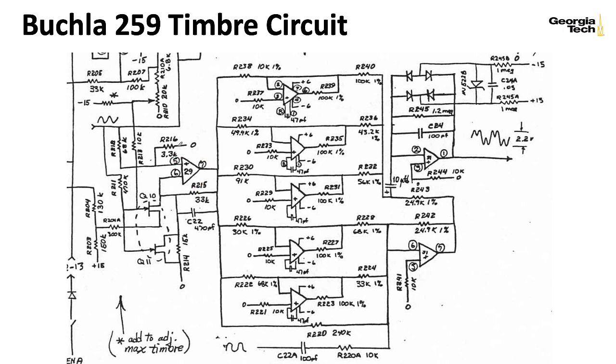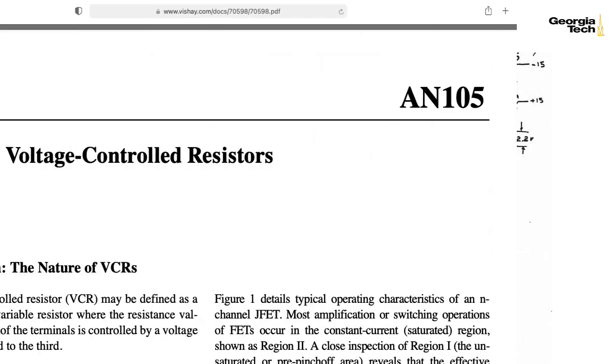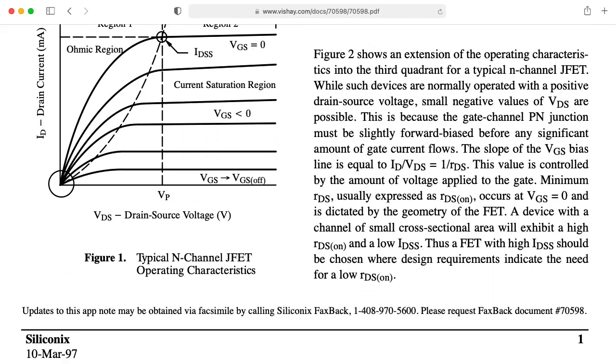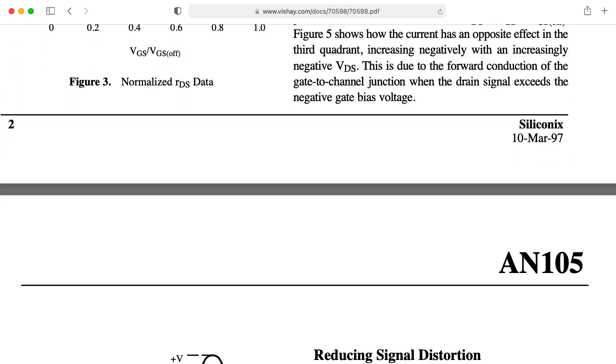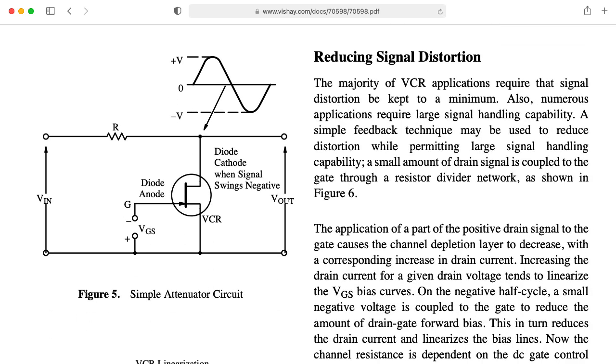Now, what I've described here is really quite rough, both in my description and in thinking about a JFET as a voltage-controlled resistance. There's a little bit of the sine wave, the signal that we're trying to control, being added in here, and I believe that's part of trying to make this work a little more cleanly and deal with some non-ideal effects and using the JFET in this way.